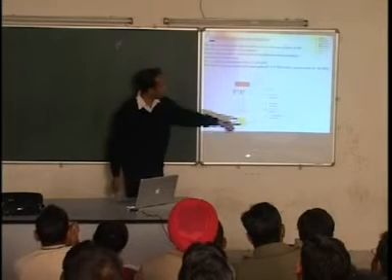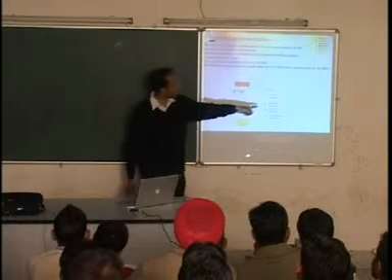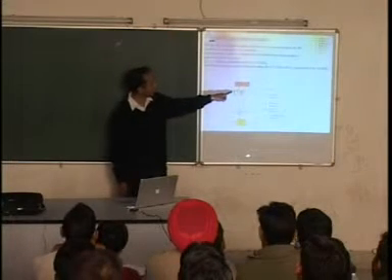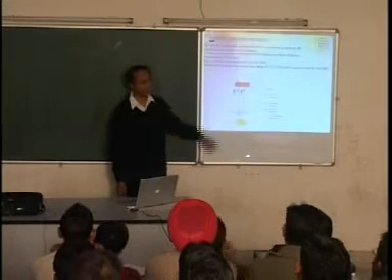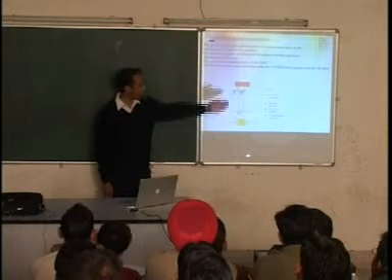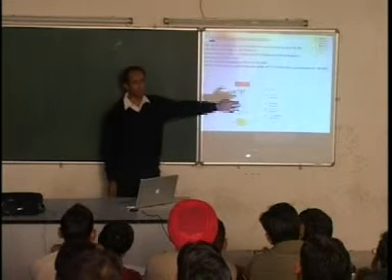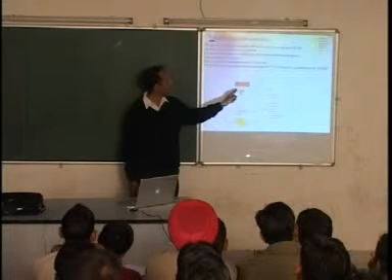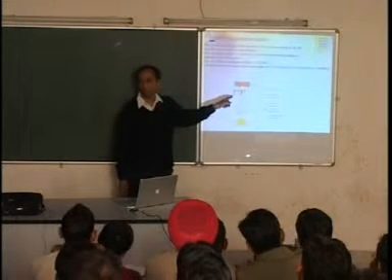If you look at the symbols here, a capacitor and a resistor. So I have a capacitor and a resistor to ground. It's a high value capacitor, 10 nanofarad. So all that 1 gigahertz, half gigahertz signal goes out there and is all dissipated in the resistor.